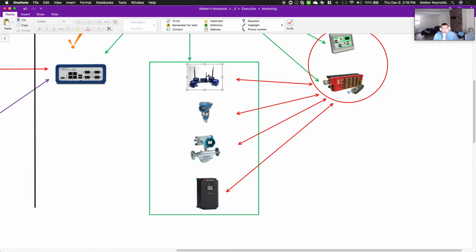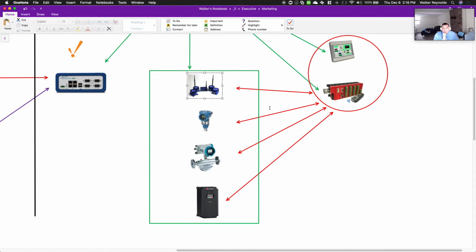That's an edge device. These are smart transmitters. You basically have no physical connection between the sensor and the PLC. It's all done over Wi-Fi, but they all speak MQTT. So what happens is these devices talk back to your PLC for process control over the native protocol. All the process control is done over the native protocol.